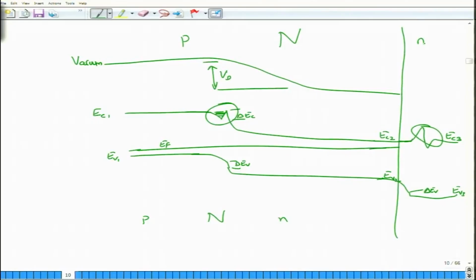Okay. This is not normally used, but we will come back to the actual one that is used in practice, but this is the idea. So, you will have three different materials. One of the materials will happen to have a larger band gap than the other materials. The other two materials will be of the same type, and the overall effect is that the energy levels are actually changing and the middle layer has to act like an accumulation layer. So, clearly I cannot put a small n on this side, I should have put something else on the other side, right.